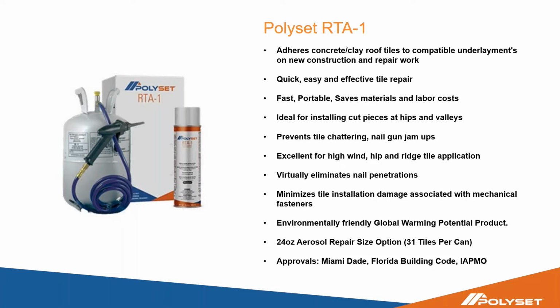For those of you that install a lot of cut pieces on your valleys or your hips, these are great for installing those. It's very difficult to install it with a mechanical fastener. They also come in aerosol sizes, 24 ounces, which can yield you about 31 pieces of tile. The 23-pound tanks can yield about 4 to 5 roofing squares. The reason I say 4 to 5 is because it depends on the tile profile. Different tile profiles require a little bit more adhesive than others.